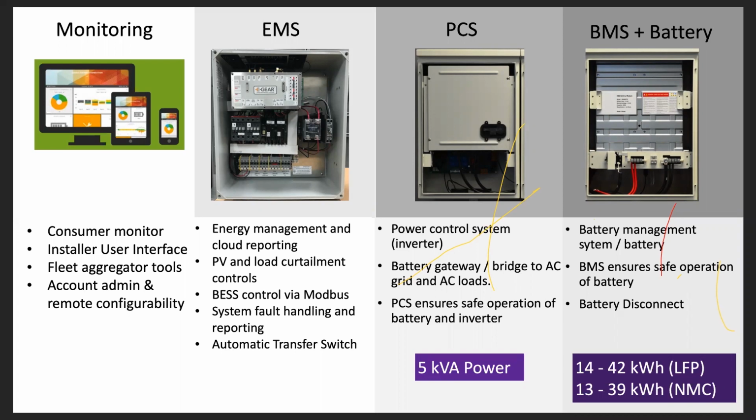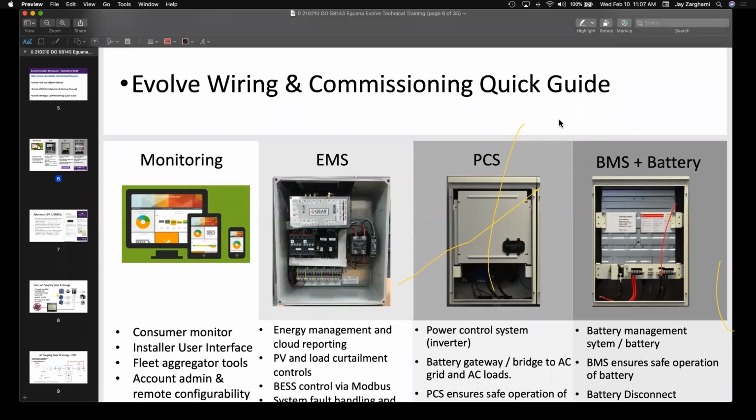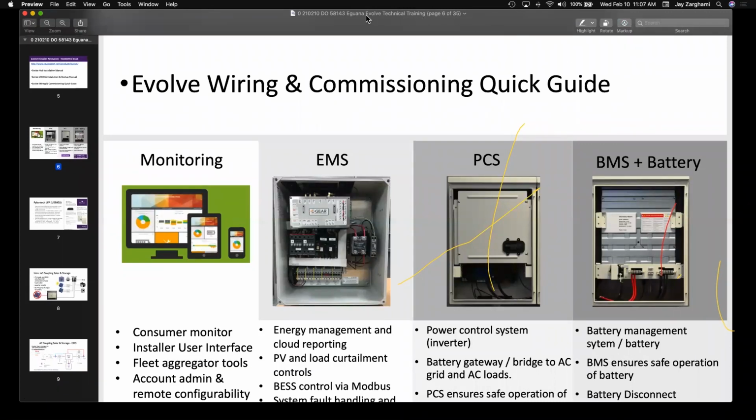Anyways, getting back to the question, as far as the transfer delay, yes, it is 4 seconds, so that in case the grid was to go down and then back up within a second or so, within a short period of time, the inverter doesn't conflict with that. And so it does have an isolation delay of 4 seconds.